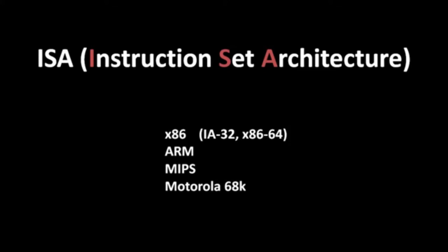An instruction set architecture tends to develop and grow over time. The x86 ISA, for instance, started in the 1970s, but has evolved since as Intel and AMD have released new processors. The newer processors support the instructions of their older ones, and they have all the same registers, but they also support additional instructions and include additional registers. So x86 is more accurately an umbrella term that covers a family of continuously compatible ISAs.